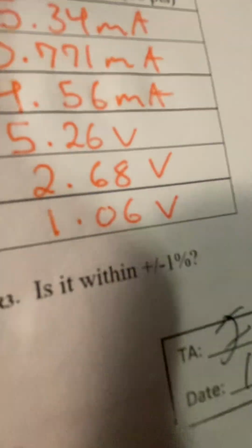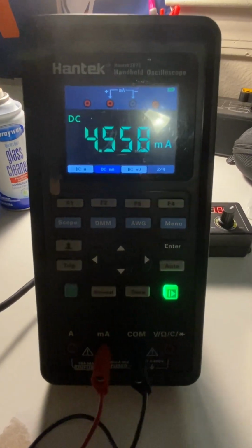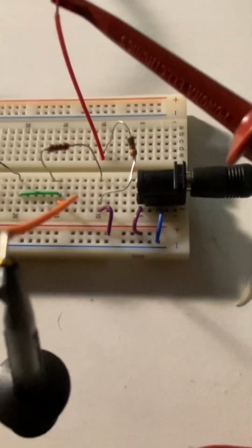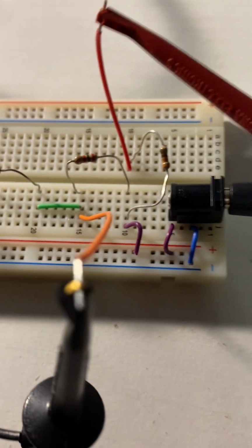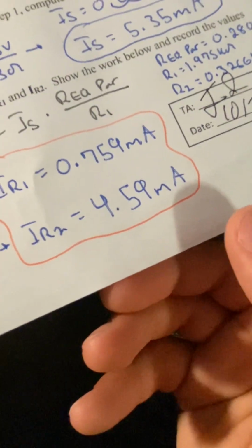So here we got current 4.56 milliamps. Here we get the same reading, and this is how you open the circuit for those parallel circuits. You put it on the other section of the breadboard, go through, and it goes back through. Then that's how you find your current, and that's what we calculated before in our hand calculations. As you see right there, 4.59, and we got 4.56. It's a little difference. There's some error in there. Normally it's the voltage because it varies.